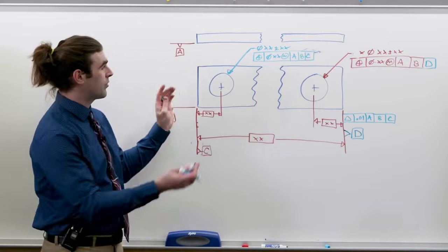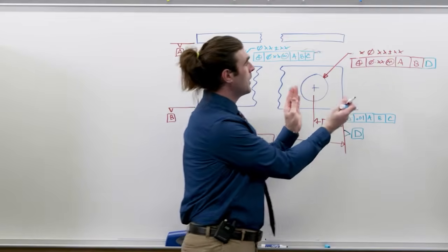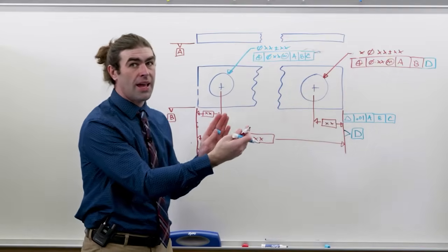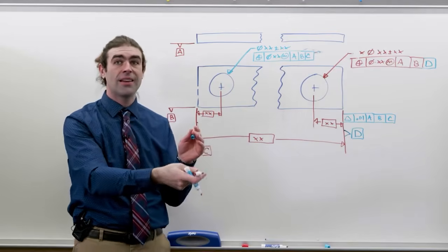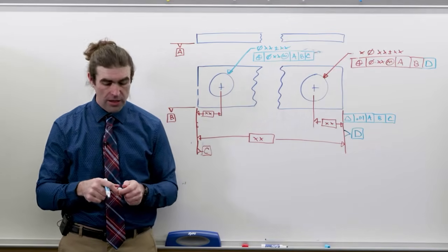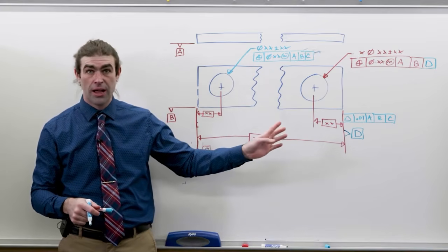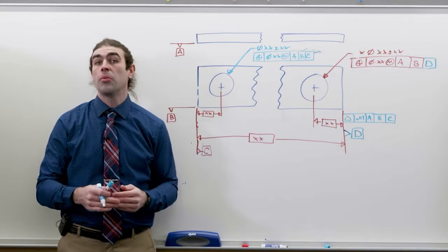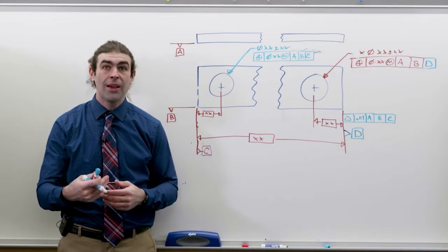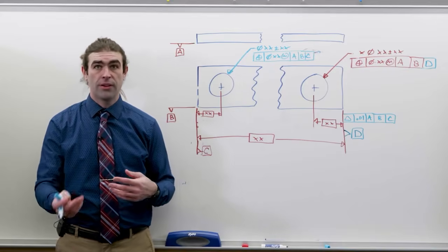If this hole is just sliding over something that has to do with one edge, it would be the same over here. You're measuring from the edge of the important side, not the total other side of the part. Okay? Whenever you do this, though, you're going to introduce extra tolerance stack up whenever you have multiple datum reference frames. It also causes inspectors to have to set up differently, right?